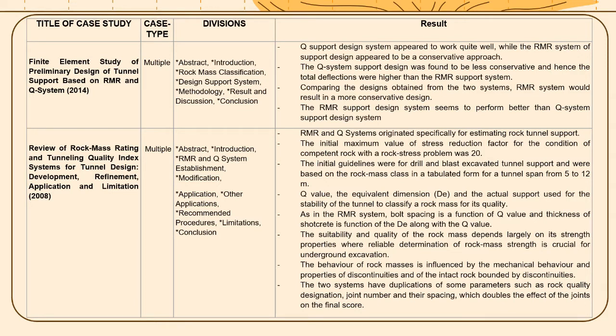The Q system support design was found to be less conservative and hence the total deflections were higher than the RMR support system. In the comparison of the designs obtained from the two systems, the RMR system results in a more conservative design. The RMR support design system seems to perform better than the Q system design.